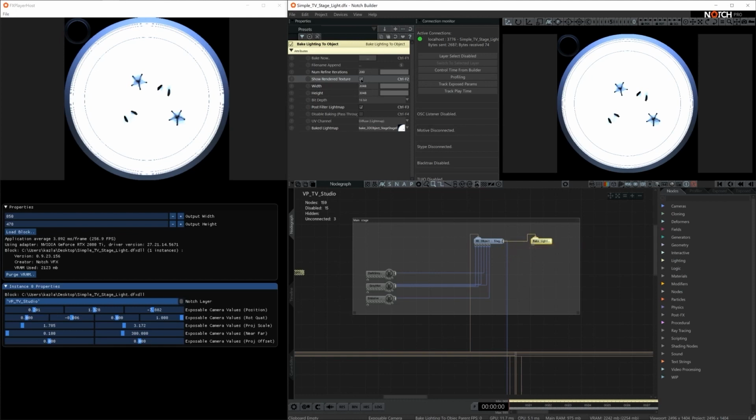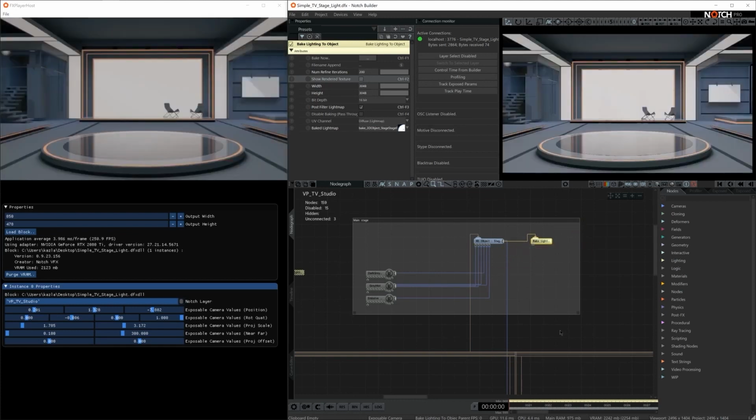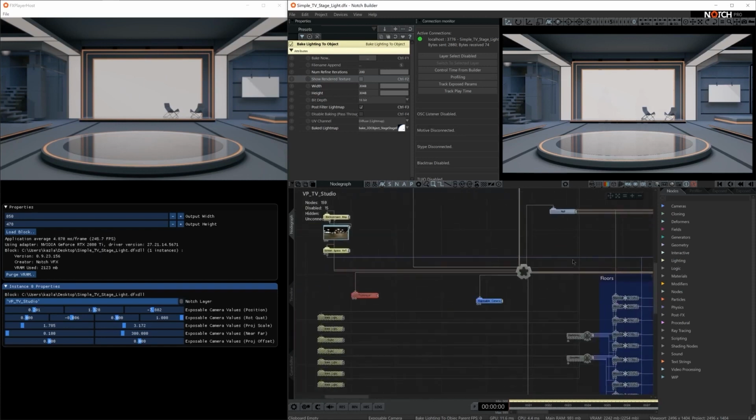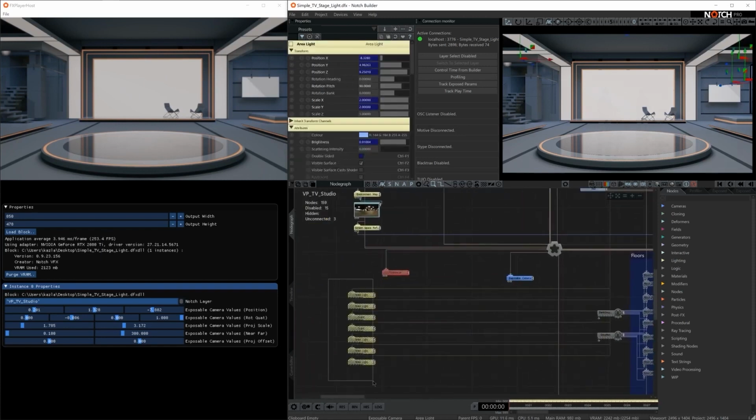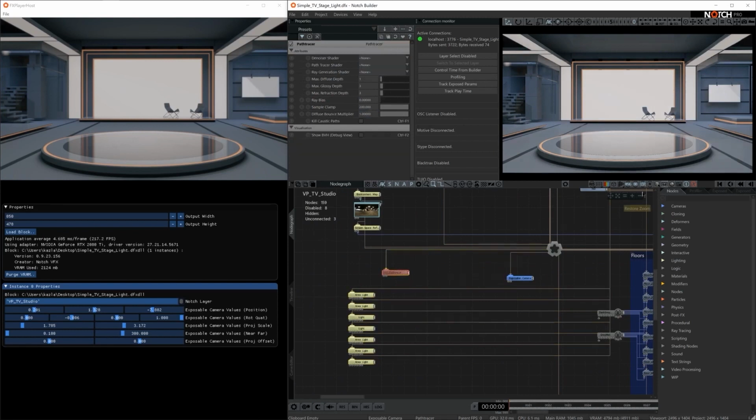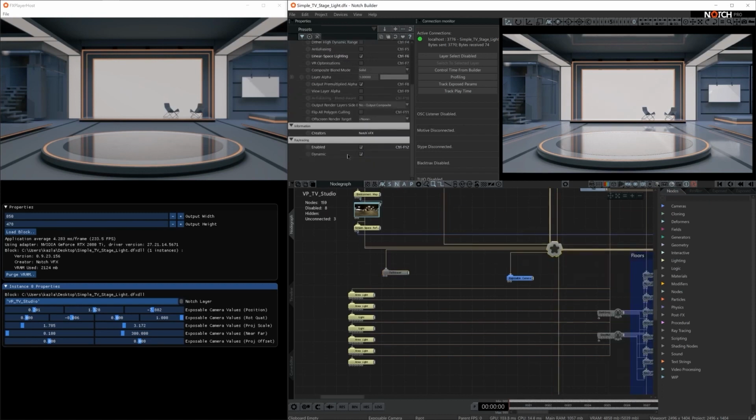In order to do that, first of all, I have to enable the dynamic lighting. So here are all the light fixtures that I should enable. So I'm going to click Ctrl+1 to make sure that they are running. And I see that I have Path Tracer in the scene, but it's disabled. So I can enable it by clicking on this UI icon or using shortcut Shift-R. And as I see in the root node, now it is definitely enabled. Great, so the dynamic lighting is working.